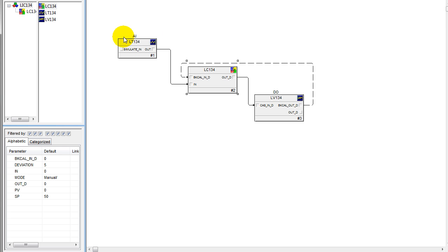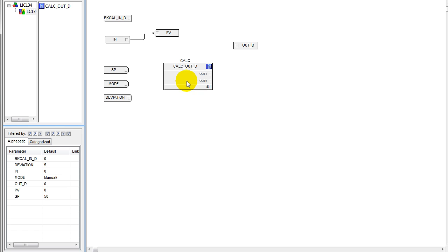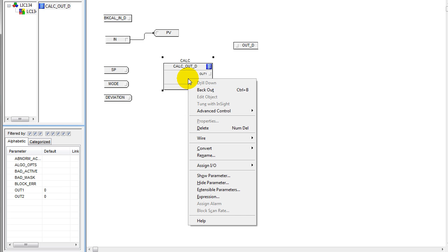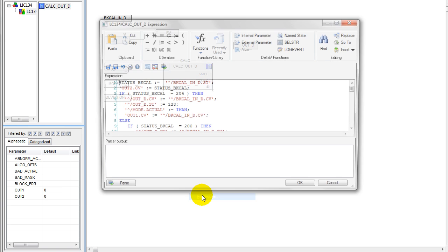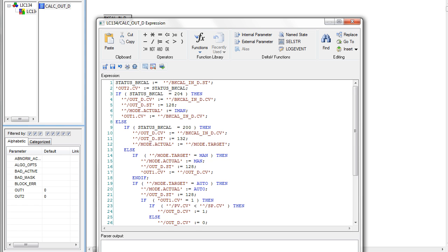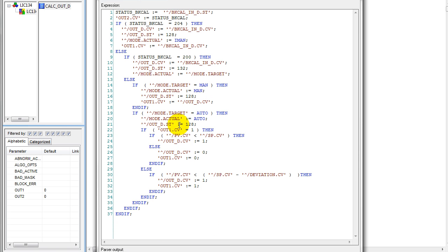We're looking at the wireless measurement here, going through our control that is dictating our output. To look at how we have implemented the control using the wireless measurement and the wireless on-off valve, we'll look at the control calculation. In the composite that is used for the control, there's a determination of whether the downstream block is in the correct mode.